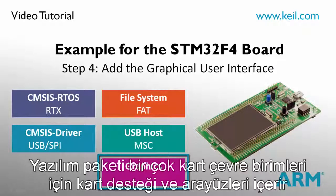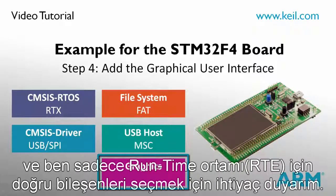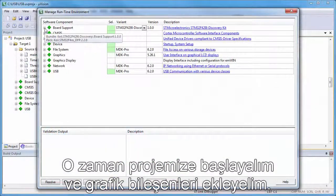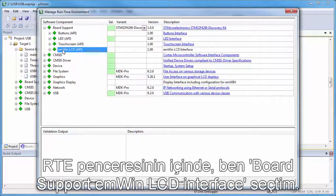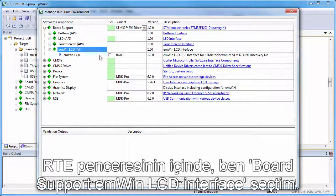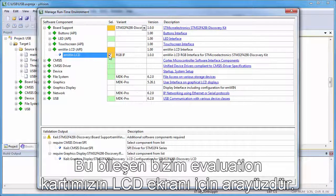The software pack contains board support with interfaces for most board peripherals, and I just need to select the right components for the runtime environment. So let's start our project and add the graphics components. In the RTE window, I select the board support EMWin LCD interface. This component is the interface to the LCD display of our evaluation board.